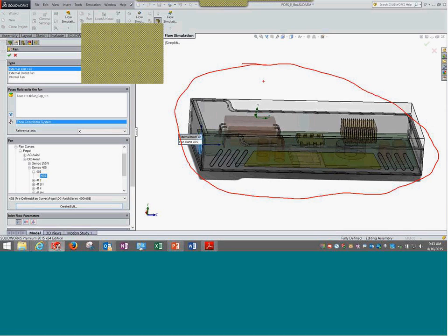one interesting fact, for deriving this curve as well, one can use a software like FlowSimulation, not only for fans, but also for system level curves. But really, the fan curves are discussed in more detail, and the system curves are not discussed, or if I put it another way, the system curves are not standardized. They depend on many factors such as the geometry. However, the curves are very localized and can be realized or replaced.